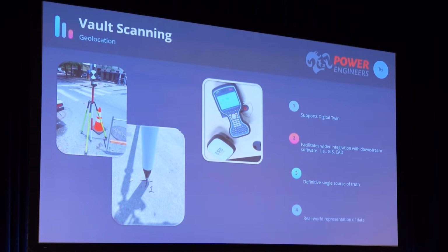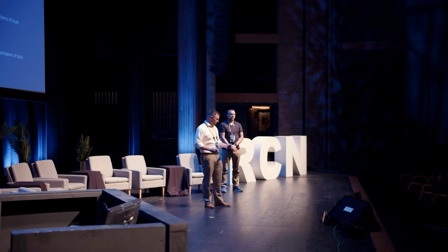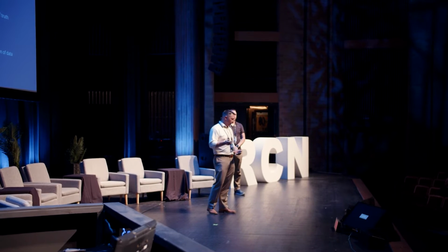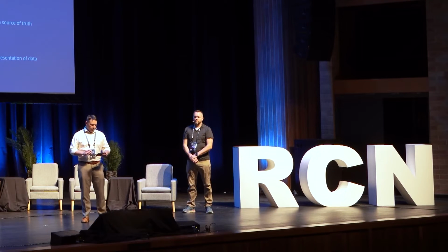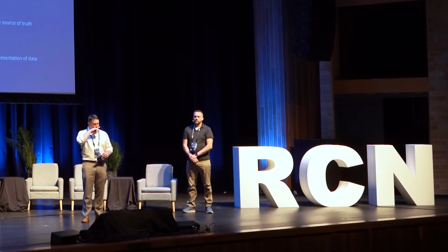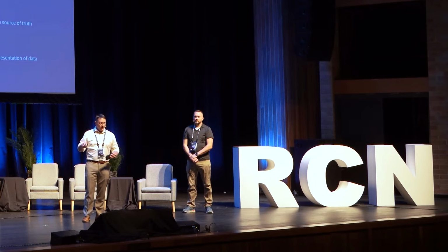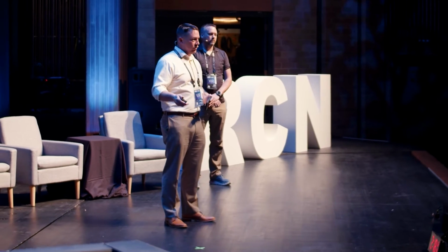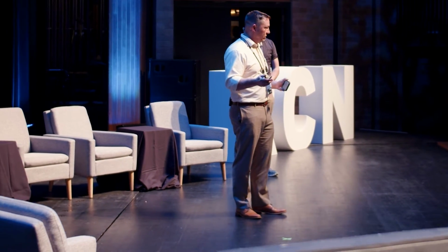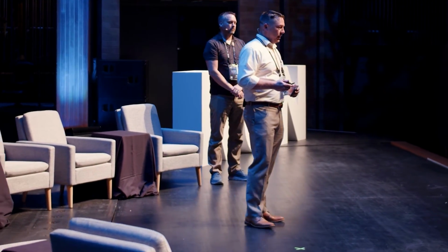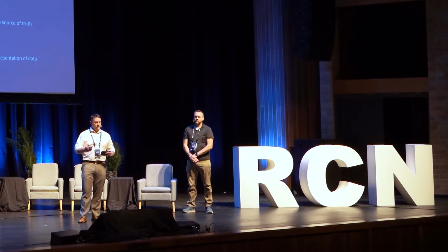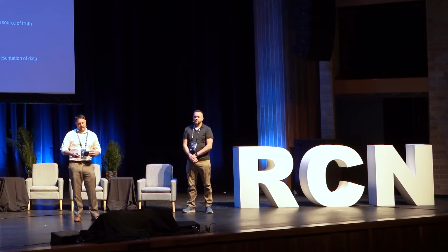Geolocation was sort of a new thing for us, and after a lot of researching and brainstorming, we figured out how to accurately geolocate just about anything. And here's how we did it. We would essentially set up points above ground and locate those points using georeferencing tools, and then scan above ground, and then we would invert the scanner immediately and locate it above the manhole.